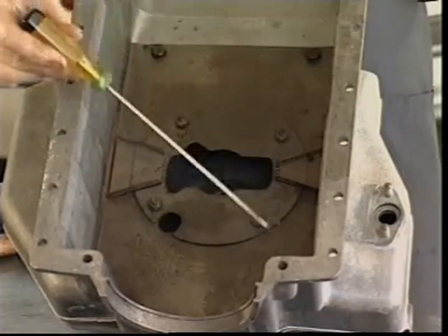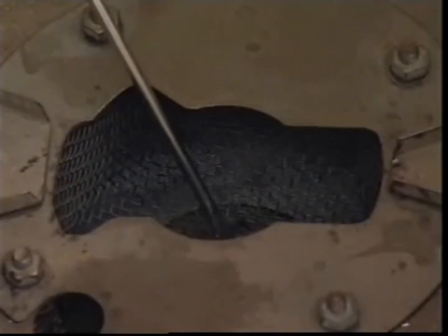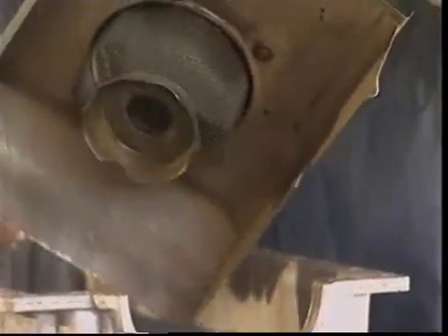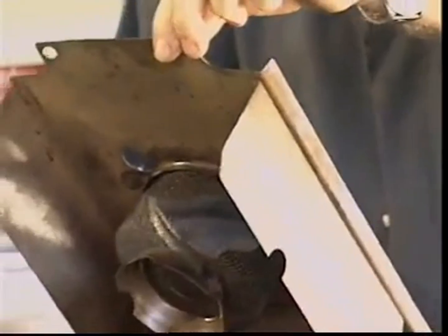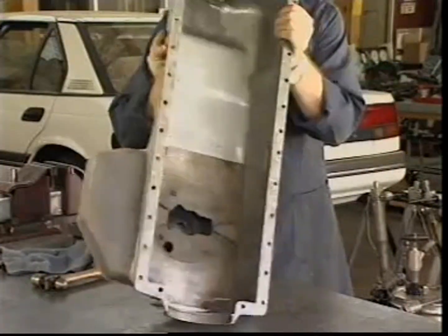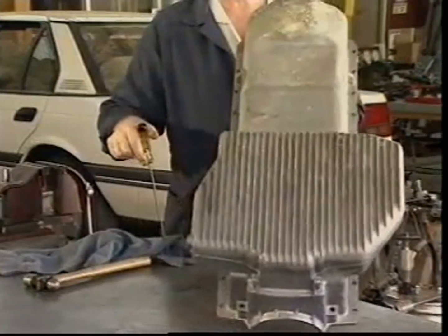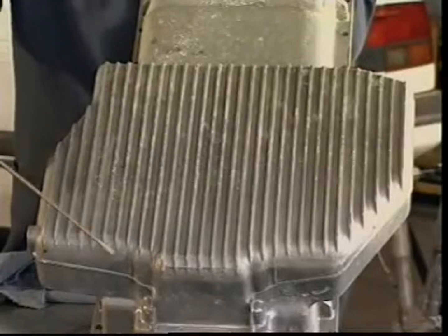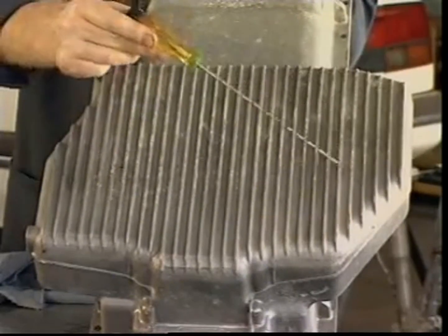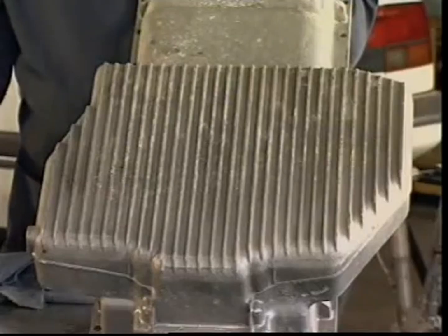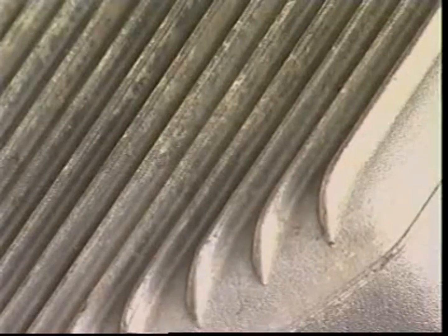Some high-performance vehicles have a windage tray fitted to prevent churning of the oil by the rotation of the crankshaft. Baffles prevent oil from surging away from the pickup during cornering, braking and accelerating. The sump's large external surface area helps heat transfer from the oil to the outside air. In some designs, the sump is an aluminium alloy casting with fins and ribs to assist in this heat transfer.